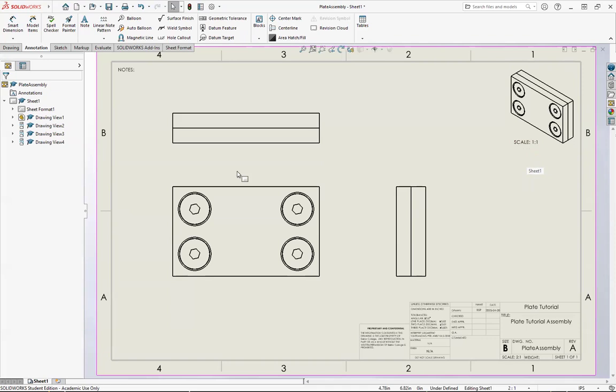So for this drawing, this is actually complete. I don't need anything else on here. Now I could add some things, but on here I don't. The dimensions and things are actually going to come from the individual part drawings. So this is just to show how the assembly goes together. We may need more views than this for more complicated assemblies, but we want to be very clear on how this assembly goes together. That's the entire purpose of assembly drawings, more so than the dimensions.